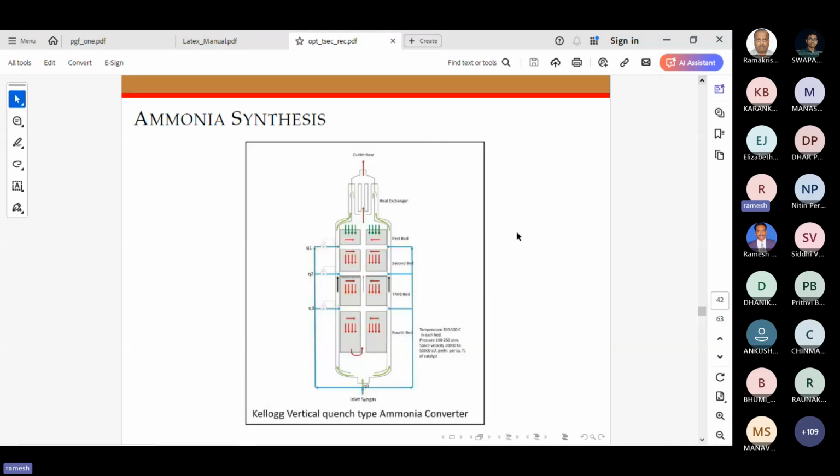So here, this is Q1, Q2, Q3. These are the three mass flow rates of the quench fluids, which are the variables here. What the final production of ammonia will be depends on how you divide the initial Q0, that is the feed flow rate, into Q1, Q2, Q3. This is how you pass these three variables into the simulation model. Then this whole reactor is simulated, and finally your output is calculated. That gives you one objective function or fitness function value.